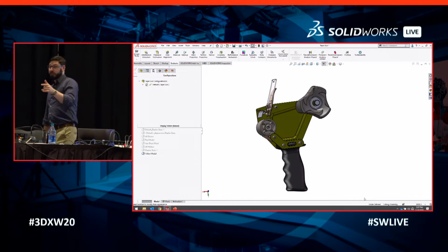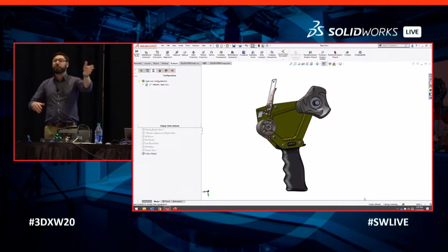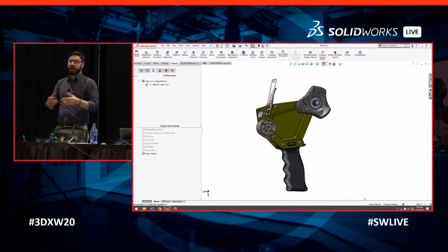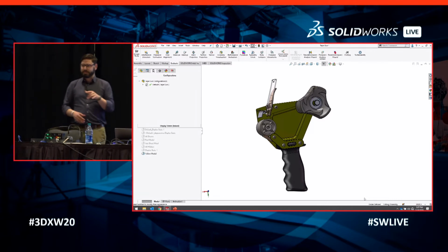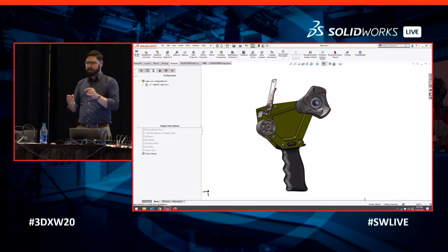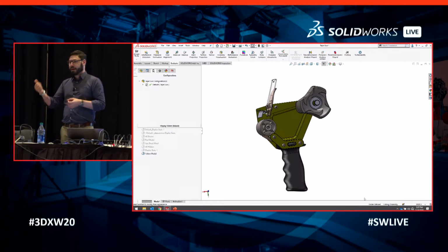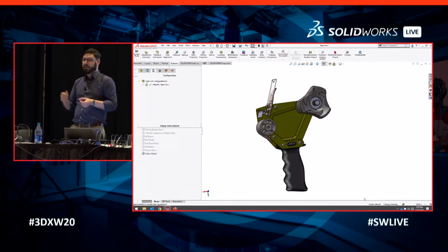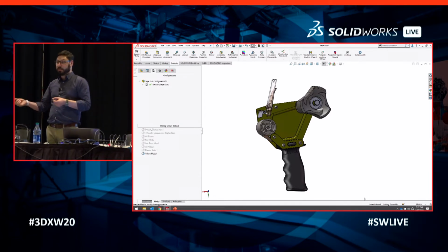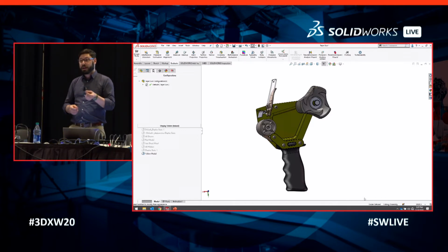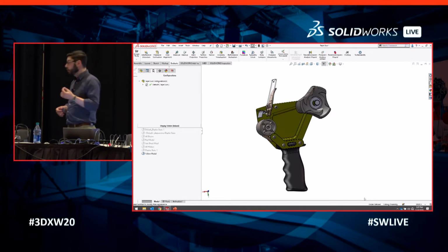That's a great question. So for those who didn't hear, the question was that's only loading it graphically, or not loading the intensity into the graphics card. That's actually not true. Because when you open up an assembly, all the shown parts will load into both the graphics card and the RAM. With SOLIDWORKS, though, if a part is hidden, when the file is open, it will not actually load the component into RAM until it's shown fully. So it actually relieves your RAM quite a bit. So it is a good strategy.